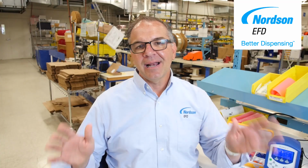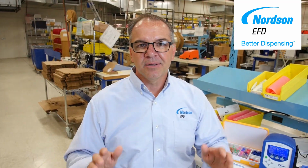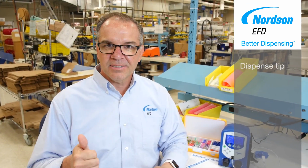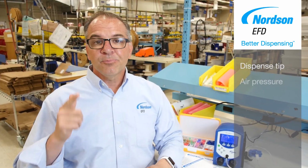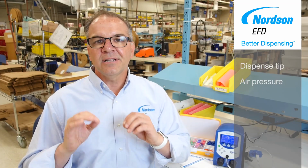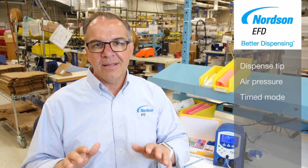Okay, we talked about a lot of things today, so let's recap. To set up your dispenser properly, you first need to select your dispensing tip. Next, set your proper air pressure. And lastly, if you need controlled, consistent amounts, always be in the time mode.